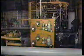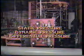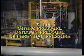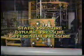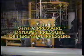Now, there are several different types of pressure that you may be familiar with or will hear about as you study fluid flow and flow measurement. However, in this program, we're going to concentrate on static pressure, dynamic pressure, and differential pressure. Static pressure is the pressure exerted by fluids at rest. For example, the liquid in this tank is exerting static pressure against the walls of the tank. As we'll see later in the program, static pressure is important in the measurement of fluid flow.